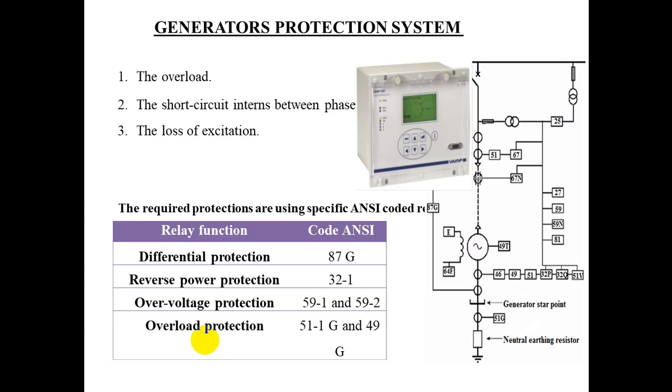Because the synchronous reactance of a modern machine is often greater than 100%, the sustained fault current fed from the machine into an external fault is invariably below the normal full load current.